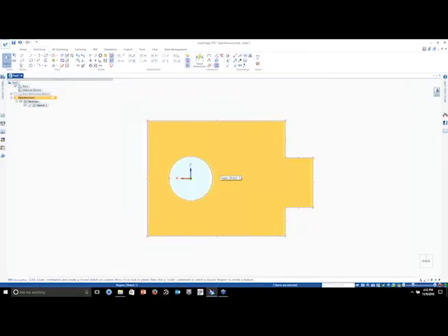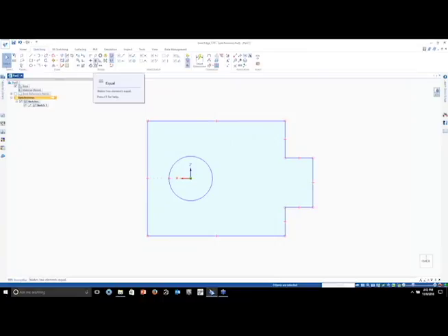All right, so let's add a few things to this. I could go ahead and make a solid out of two different regions, but just for this purpose, I'm going to use a trim tool. So under your draw menu bars, you have trim, corner, adding radiuses, etc. So I'm just going to go ahead and trim that away. So then that leaves one region. But again, my geometry is not fully defined, it's just kind of floating in space. So we need to use some dimensions to define the overall size and shape. And we also need relationships to help along with this.